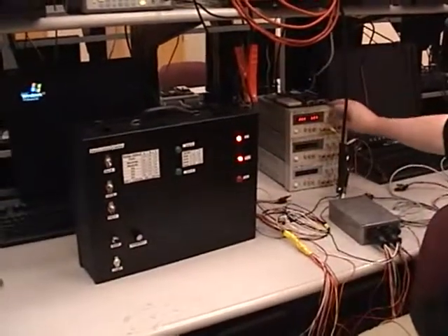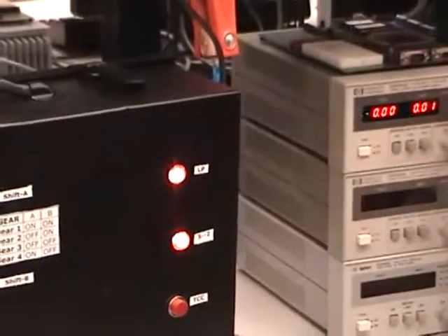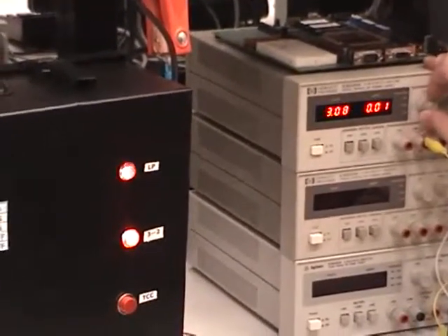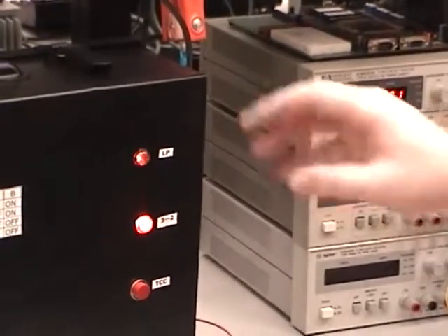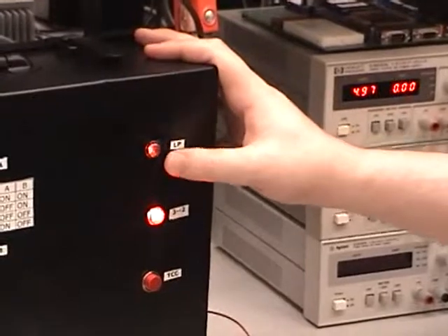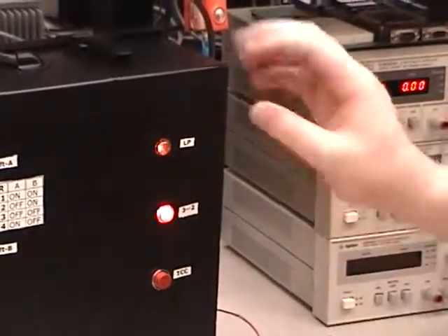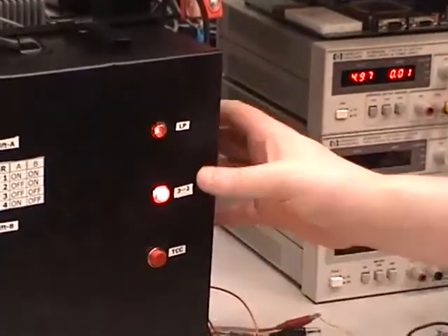So right now, you can see with zero throttle, it's showing you that there's not very much line pressure because we're giving it a big PWM. And then as we increase to maximum throttle, you can see that there's a lot of pressure now in the transmission because we're hardly letting any fluid past. So it's all building up, causing a high line pressure right now.